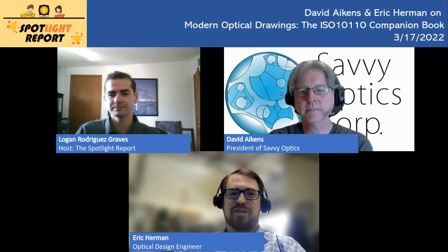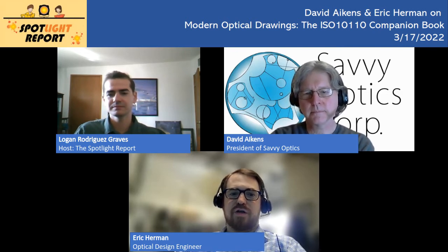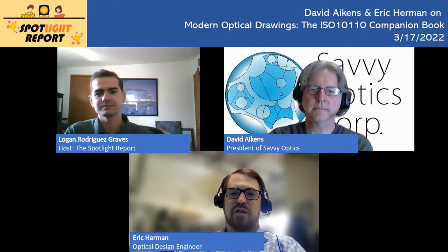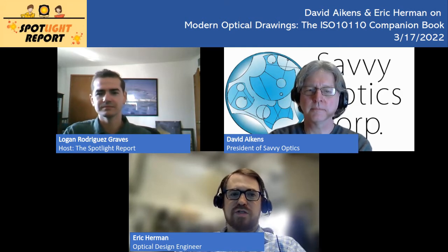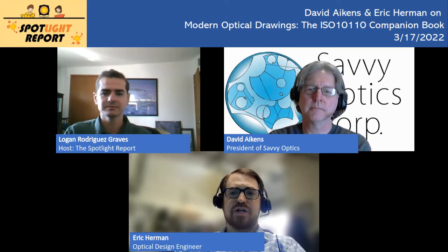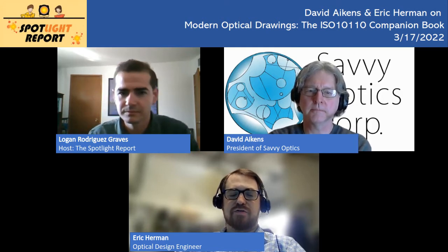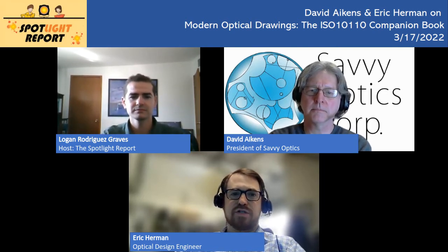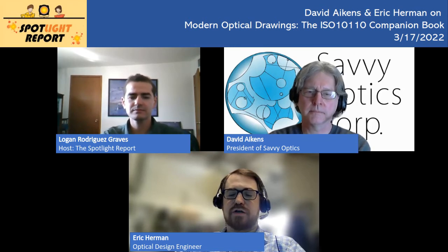So it's going to be different things at different points. Bubbles and inclusions are going to be within that part, and they may be something that you can visually see with your eye. It may not impact your optical system too much, but it will still have some effect. Stress birefringence comes from when they're melting the glass, and if they're not annealing it properly, you're going to have those sorts of stresses, and you might end up having polarization issues because of your glass in particular.